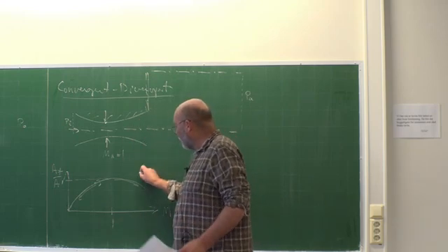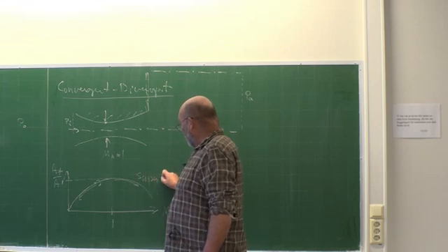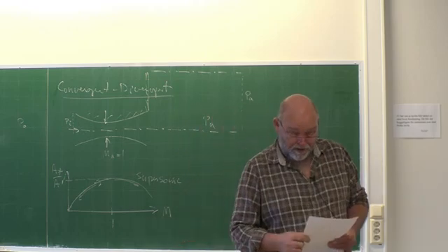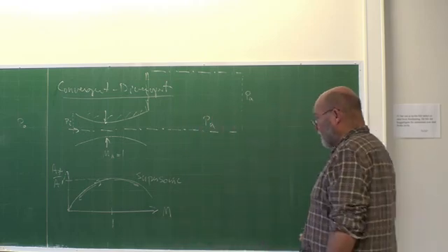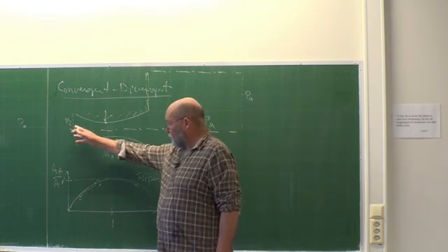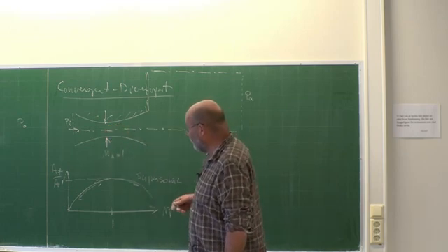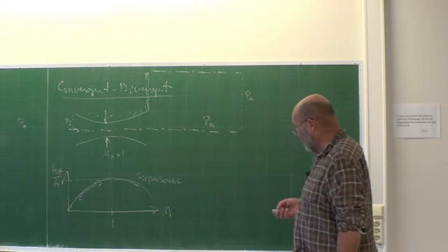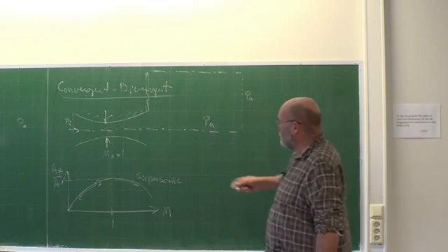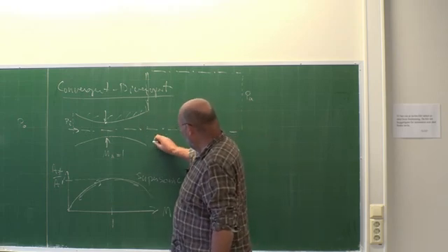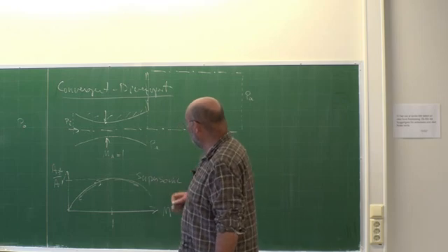And then we will have a supersonic situation. Meaning the velocity is going to increase all the time, even when the nozzle is expanding. And then it's a question, what's going to happen here? We will have a pressure, say, the exit pressure here.